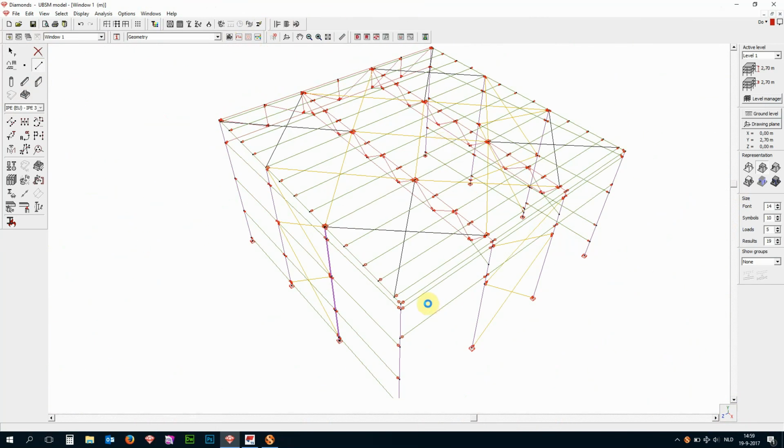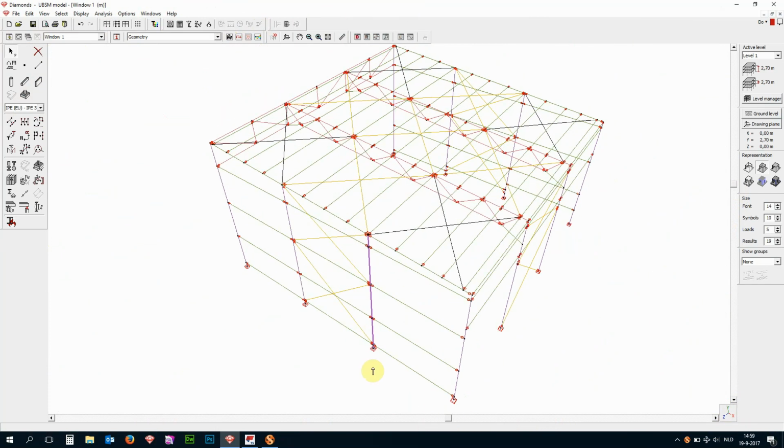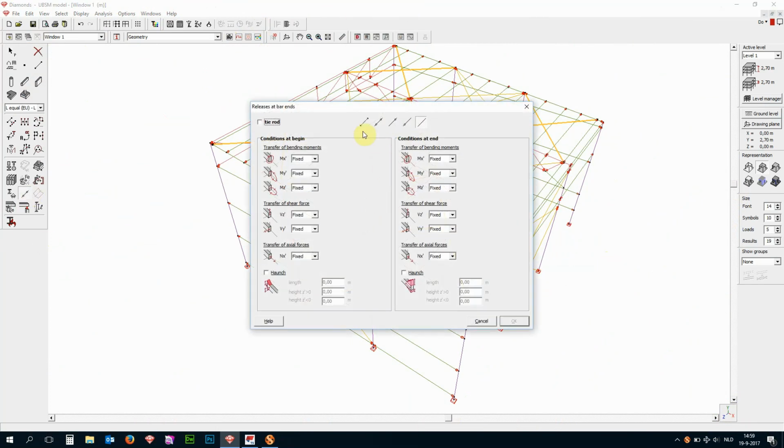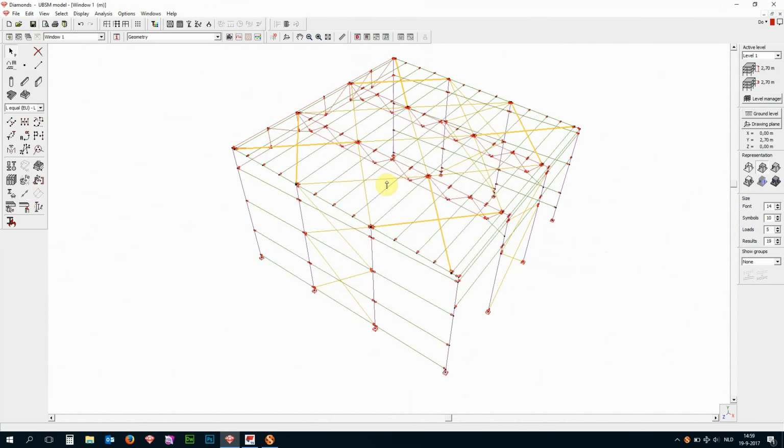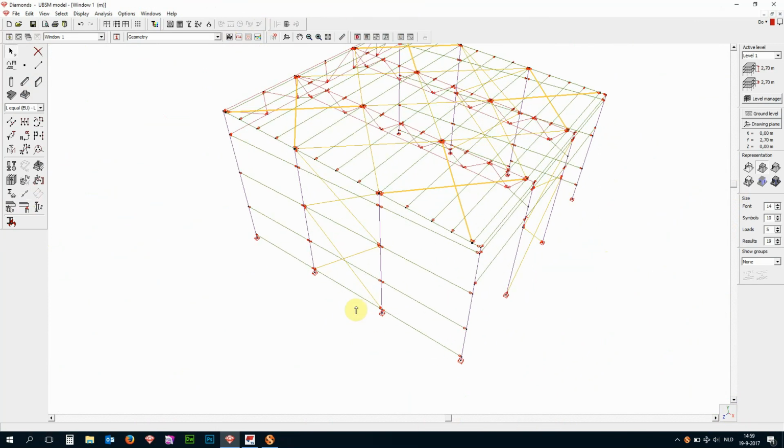Here we are. And for the cross sections now, I'm just going to click the right mouse button, copy properties, and with the control button I can select all new elements and paste the section material and type. The only thing I need to say over here is that this is a tie rod. Okay.